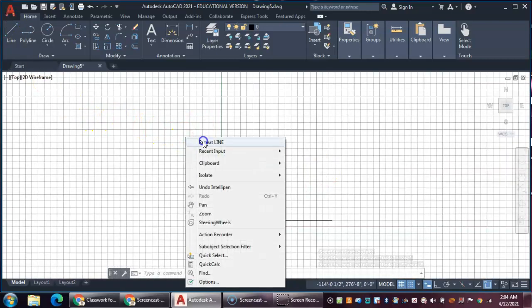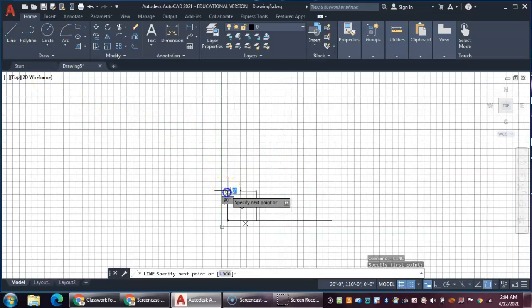So I'll right click, repeat line, but now I'm going to do it up here. 240 feet. So tab over to the 90, click, and we'll cancel out that. So now I got my first base foul line, my third base foul line, and last it wants me to